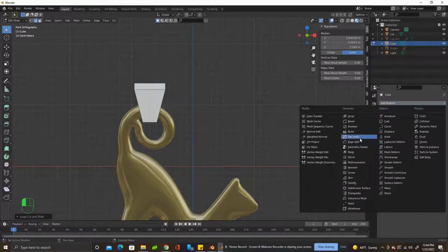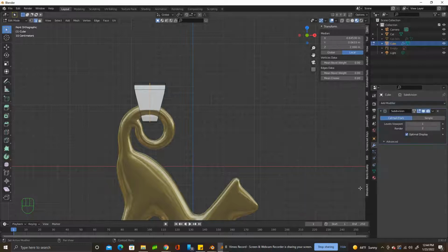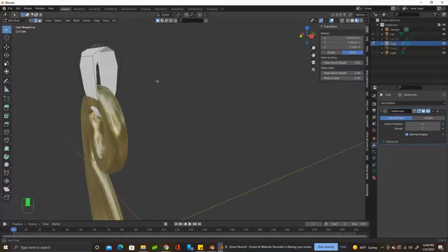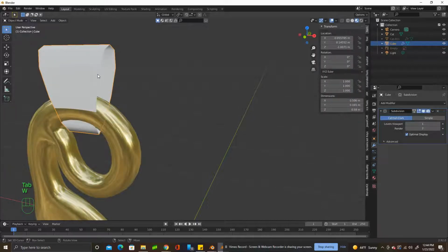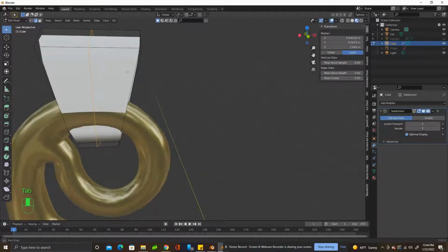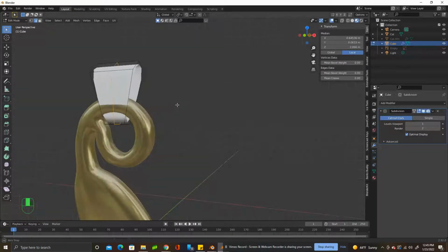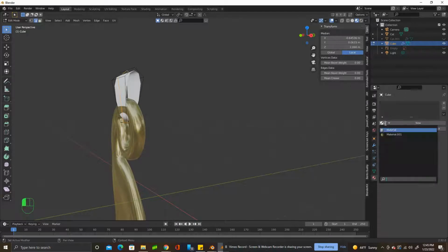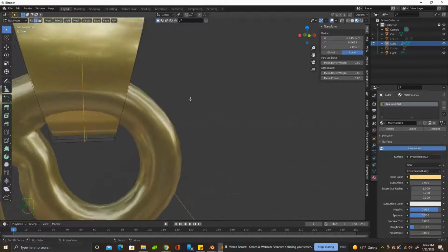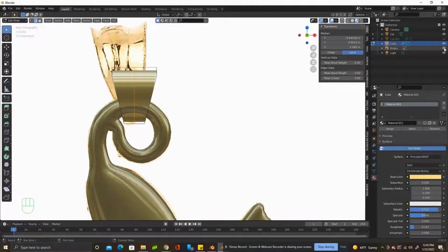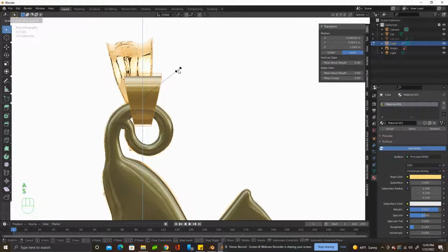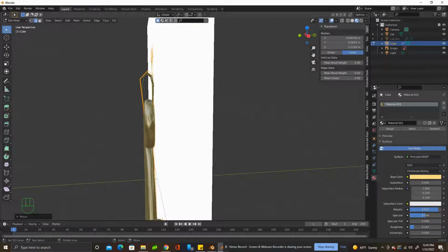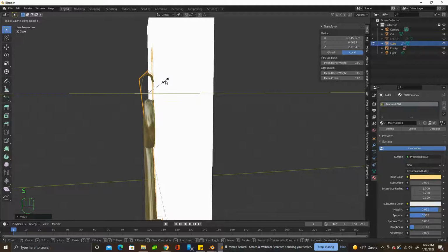And let's do the subdivision surface modifier. I'm also going to shade smooth, object mode W shade smooth. And here's where you're going to see where you need to make some more adjustments. I'm also going to go ahead and add a material to it. That way I can better see what's going on here. Alright, so it looks like this is a little longer, so I'm going to scale it on the Z-axis, bring that up some. Scale it on the y-axis.